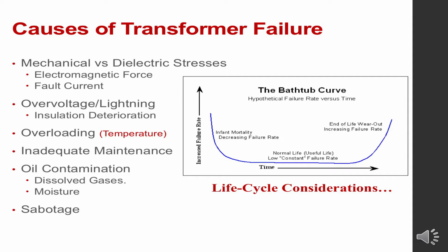Now, this is an important consideration with transformers. The general rule in an alternating current system, with anything that has a coil of wire in it, is that it's a good idea to assume the potential for higher failure rates when you first energize the device. So for example, with a large substation transformer, it would not be unusual when you first energize that device to let it soak. In other words, to energize it but not load it with any current. We'll let it soak for a period of time, hours, even days sometimes, to allow any internal faults that are going to develop to happen before we actually load the transformer and start putting it into service.